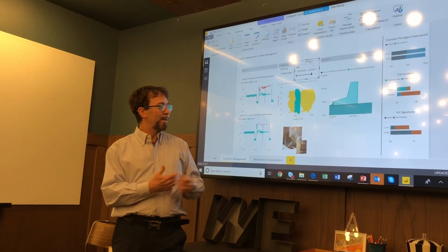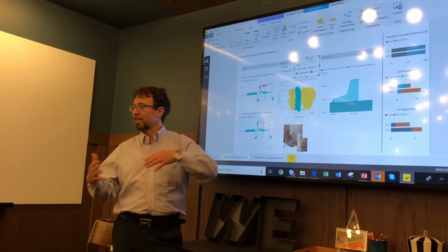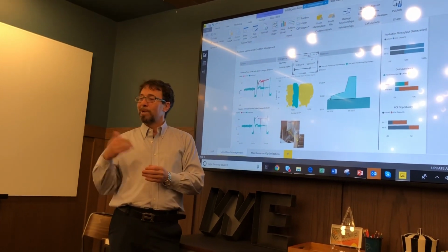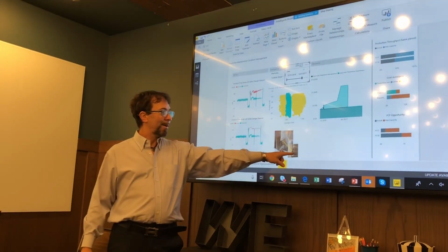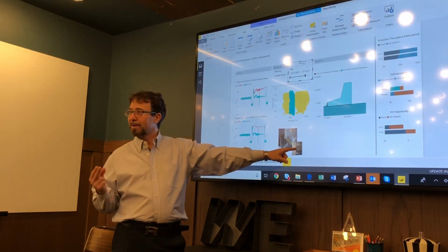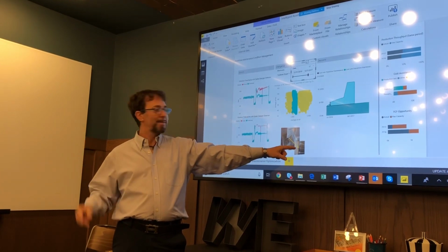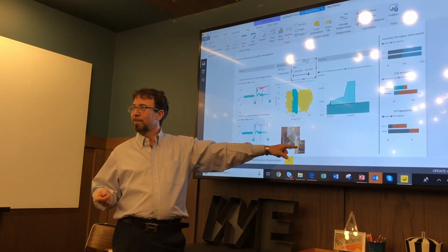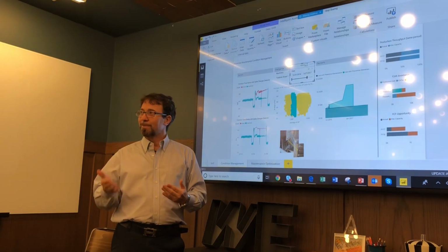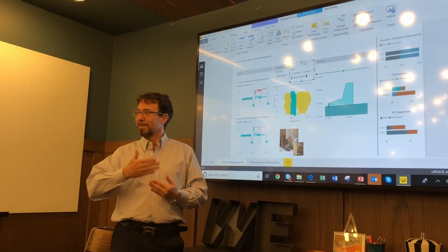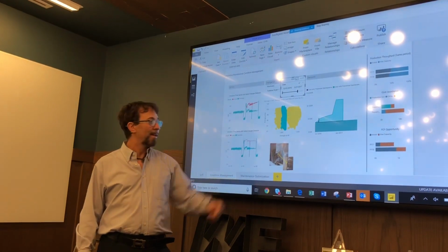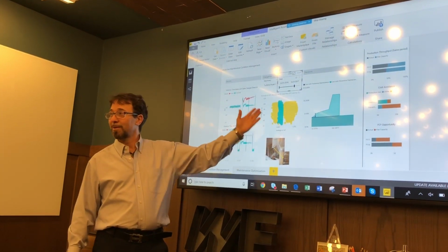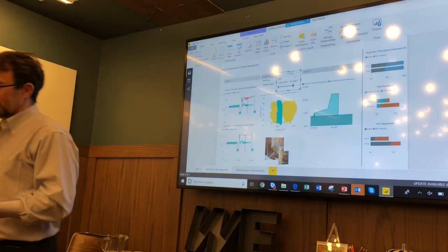And so what we find out, doing some research with the expert, is that when a certain type of harmonic comes up, it means that the supporting bracket of the blades has broken. Yes, the turbine still works, but it's vibrating more than before. And if you continue, it will continue to break others, and so on. So we know what to do, and now we need to figure out how to intervene.